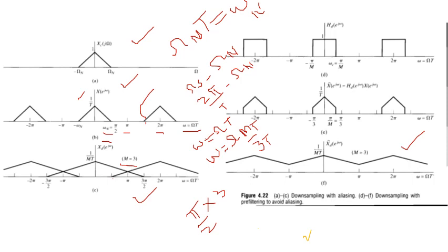Why have we lowered it? Because we are using m equal to 3. So our sampling frequency is not twice the signal bandwidth; it is less than twice. Once it is less than twice, the copies will mix up. So you can see here our copies are mixing up. This point pi by 2 will go to 3 pi by 2 because in frequency it will stretch up.